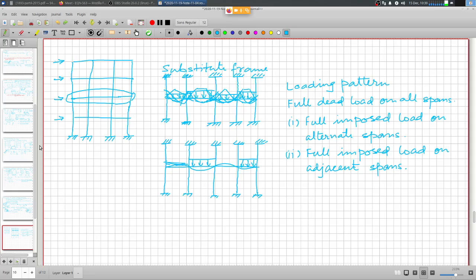So once you have the lateral forces coming onto the structure, then obviously you can work out the member forces, and then add them using the different load combinations, and of course when earthquake load is applied, then the dead plus imposed load weightage is reduced for that particular member forces.